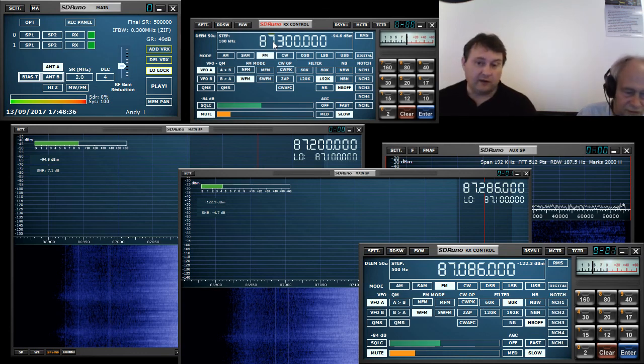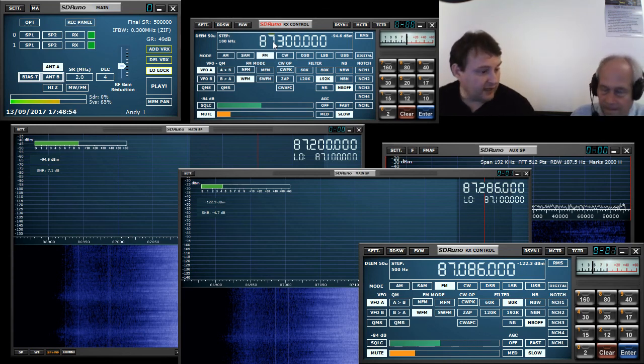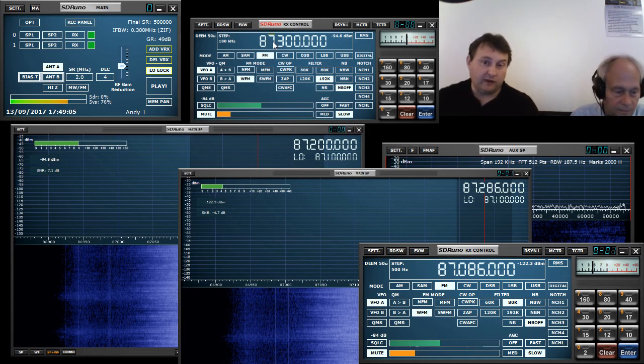Yeah, because there is an algorithm in the API to do DC offset compensation, and that will remove part of the signal at the LO frequency, or effectively at the LO frequency. And so if your carrier is there, you'll have a problem. So in AM, if you use 0IF, just make sure your LO is offset from the VFO, or use low IF mode.